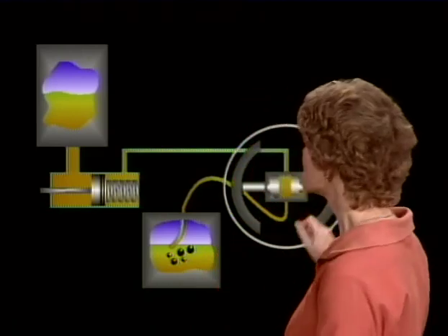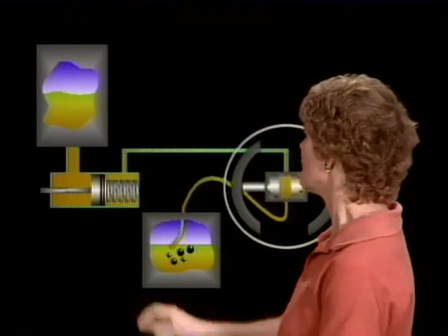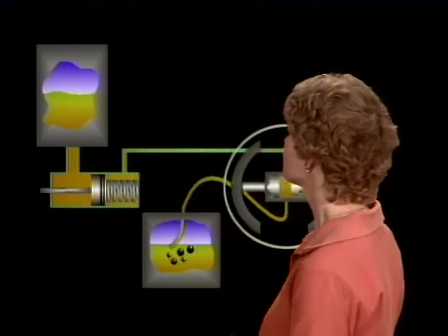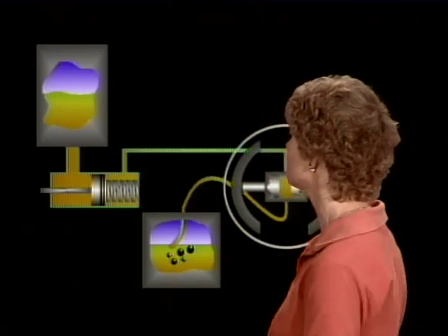Now, how do you tell when you've got all the air purged out of the brake system? Well, what you do is you submerge this bleeder hose into hydraulic fluid, some kind of container with hydraulic fluid in it, and you watch, and what you're watching for is air bubbles. You put pressure on that master cylinder and you watch as the air comes out, and eventually all the air bubbles will have escaped, and at that point you finish bleeding the brakes. You've got all of the air out of the system.